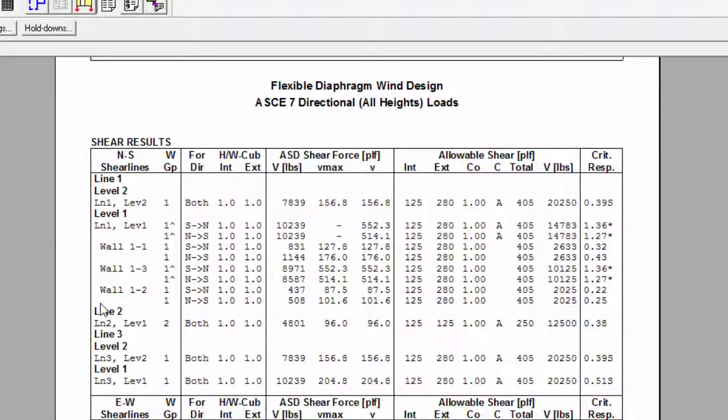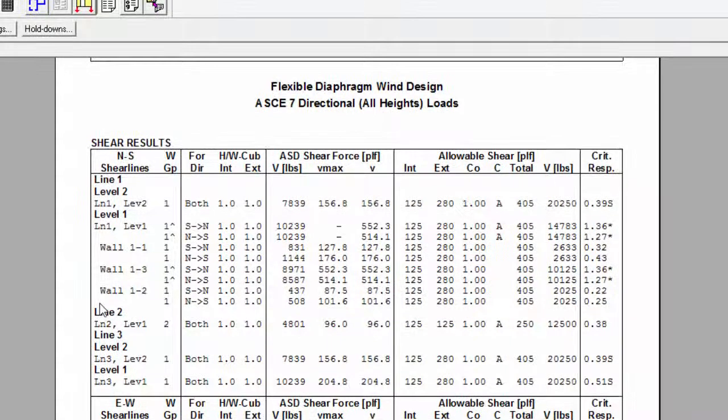To save space, the height to width aspect ratio factors and the unblocked factor CUB were combined in the same column, as they never occur at the same time, because the aspect ratio factor only applies to blocked walls. Therefore, proper attention must be given when interpreting these values, as they could stand for two different factors for the two surfaces. The int stands for the interior sheathing of the wall, and x stands for the exterior sheathing of the wall. I will demonstrate a few examples of how the value of the factor changes depending upon the material and height to width ratio.